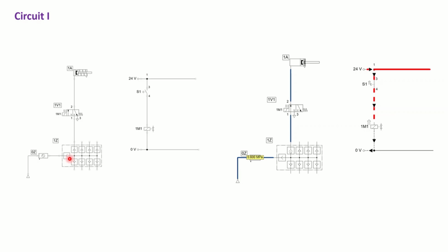What we have in here is a directional control valve with 3 ports and 2 positions, in normally closed condition, right? If the air supply is in here, it cannot operate until this valve is in the second position, which is an open position. From there the air will pass inside this single acting cylinder.